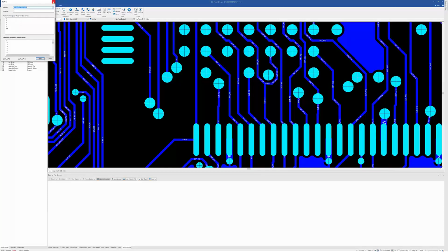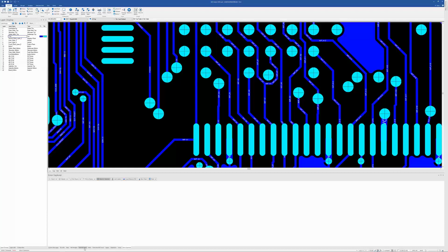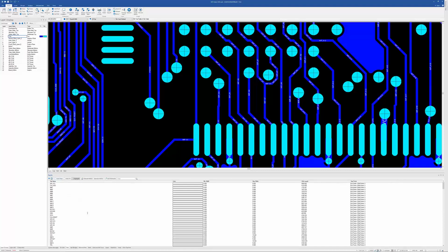and find those. But there's also a table for that, and quite frankly, I use the tables. So external nets, if they're present, this particular design doesn't have them, but most do, would be your intelligent net names, these names here. And then your nets typically are the Gerber extracted, where we just put a number on them. Either is acceptable, but you probably want these more intelligent names as you're looking at the data. Okay, so those are some of the viewing options that we put in here